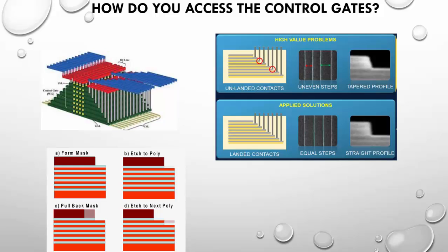The lower three frames of this photo show the ideal: steps are evenly attached and profiles are straight, leading to a reliable connection. One fortunate thing about the etch process is that a layer can be specifically etched through various means, like etch chemistry and the color of radiated light, and the etcher can tell whether it is etching one material or the other, and can be stopped as soon as it reaches a new material.